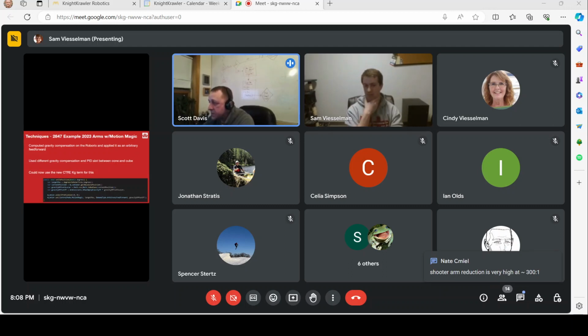Okay. Nate just commented it's 300 to 1, and we also have a spring assist, so it's actually neutrally buoyant at about 30 to 40 degrees. So with no power at all, it's neutrally buoyant about halfway through the rotation. So we've done a pretty good job of making gravity sort of a non-factor, and then we have a high gear ratio gearbox.